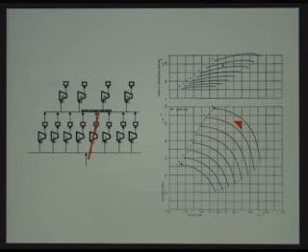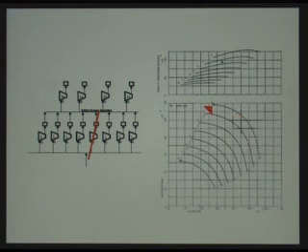Well, this 12.5% of the gas being put into this header now suddenly wasn't going to be there. These machines were still pulling at the same rate, so the interstage pressure starts to drop. And so all of the high pressure machines started to draw from a lower pressure source.